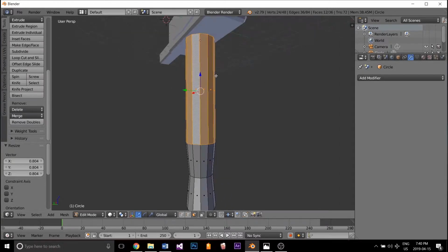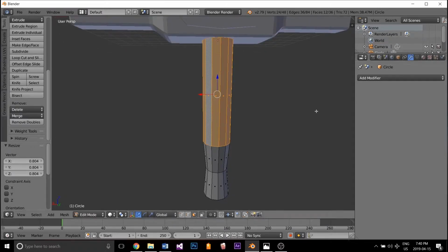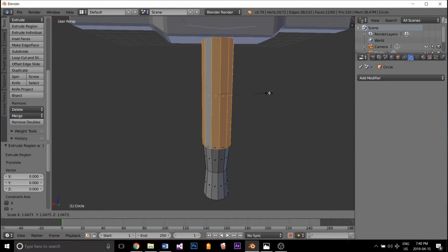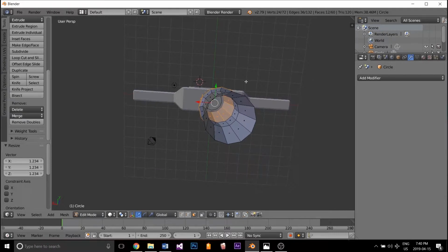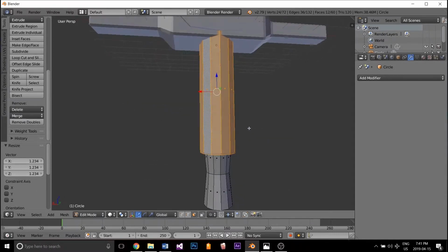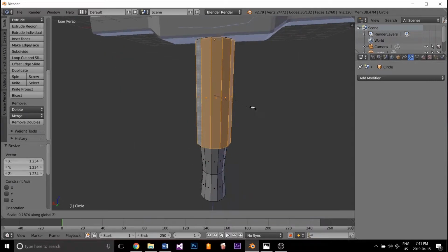So I'm going to extrude the whole way around. If we click on a face, Alt, and then click on the other one closest to the line, it's going to loop around and get the whole loop. Here I want to extrude and then click right away. That's going to keep the extrude at the origin point of where you were starting from. And then I want to scale. So we're going to hit S and then move our mouse up a little bit. And now we can see that we've moved the extrude level out, but it's just too big for the handle to look right. So we're going to scale on the Z-axis as well, down.